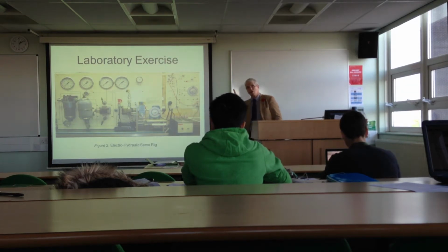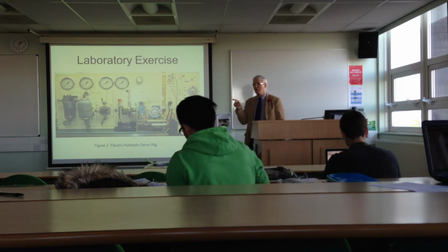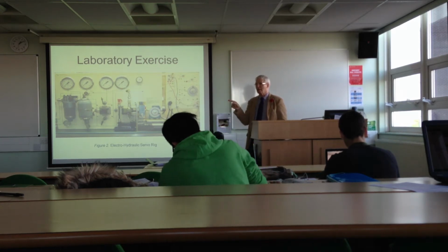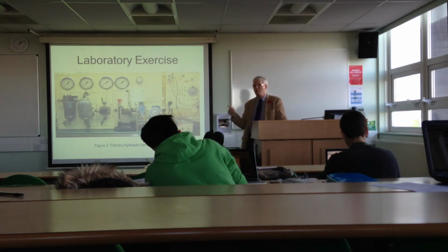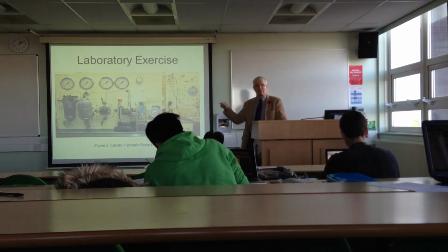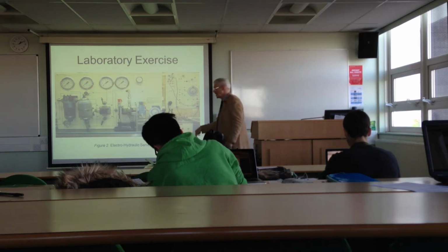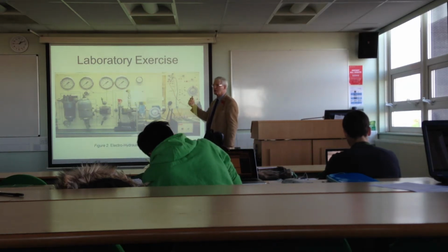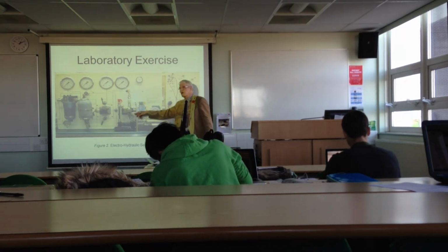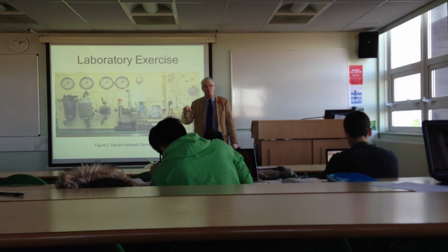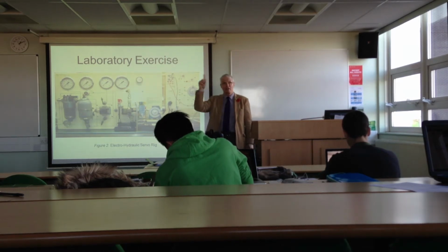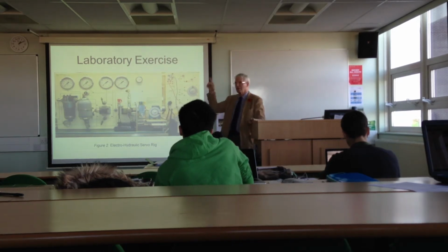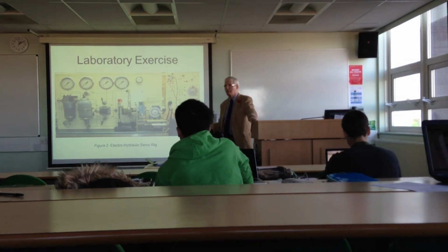We know how much oil the motor takes for every revolution, so we can calculate the flow rate. And I said that's exactly what a petrol pump does. There is a pump down in the tank underneath, pumping up petrol or diesel out from that tank through what is effectively a hydraulic motor. And the output from that hydraulic motor is actually just clocking up the gallons, the litres, and the pounds for you. So the more it goes through, the more it turns.